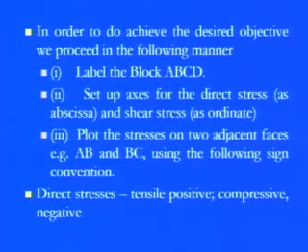First of all, looking at the sign convention of these stress components, there is a direct stress component. If there is a pulling in the normal stress, that means there is an extension, we always take it as positive, and that is known as tensile stress or tensile loading. And if there is a compression, where the internal intensity of the forces tries to go towards the outward direction, that is a compression inside the object or from the external surrounding, always take the negative direction. So for normal stress components, which is a pretty standard thing, tensile is always positive and compressive is always negative.